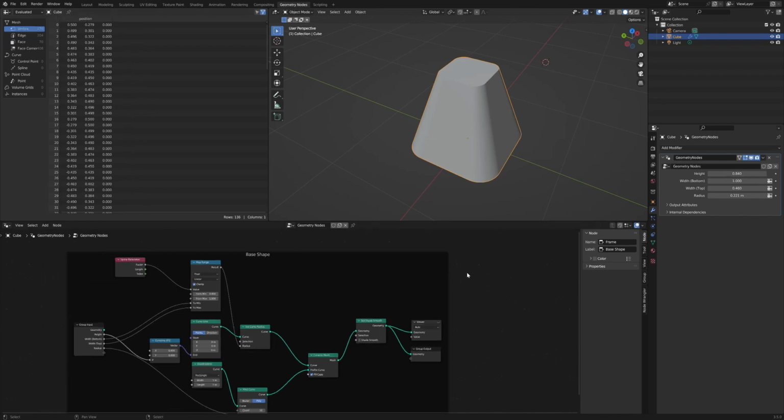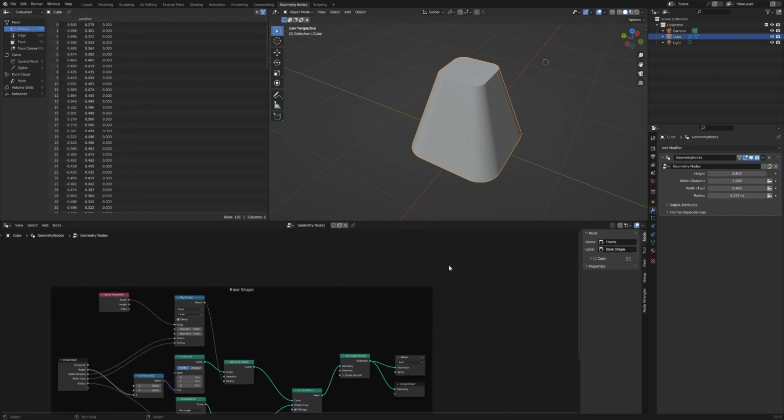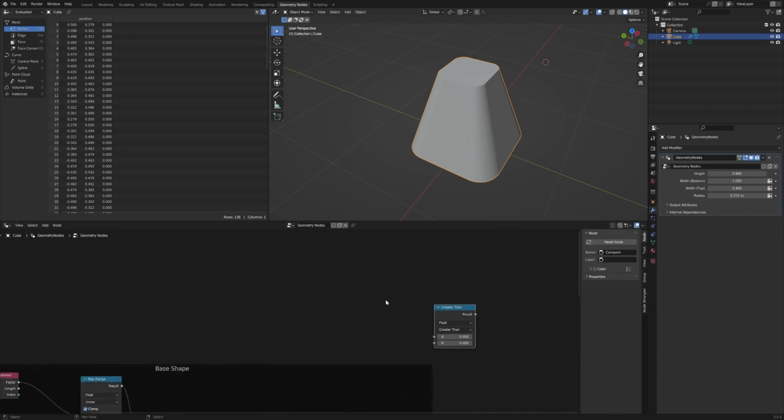And what we're actually going to do first off is add a new node, which is Shift and A. We should have explained that earlier for those that are new, and we can do a compare. And what this will do is take in a position of each of the corners. Now by default that position actually is the position of each vertex, and we can separate that out, and what we're going to do is separate that and compare that against the